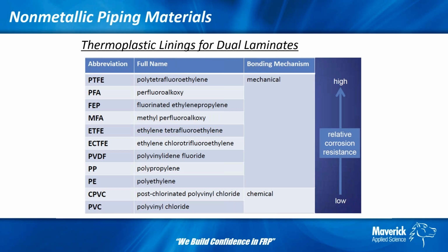Even if we measure the thermal expansion of the pipe itself, with a coupon, say, and bring it up to temperature, we don't see a substantial difference in a dual laminate versus a straight FRP, because to some extent FRP has a similar effect, given the high resin content in the corrosion barrier. Not nearly as dramatic as the thermoplastic, obviously, but similar. Because we have good bonding practices and good execution, generally you're not going to see the lining separate from the FRP structure.